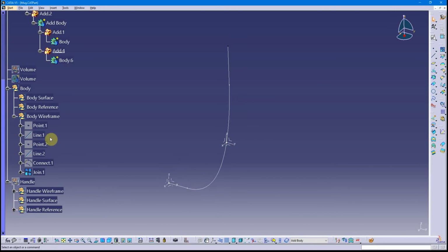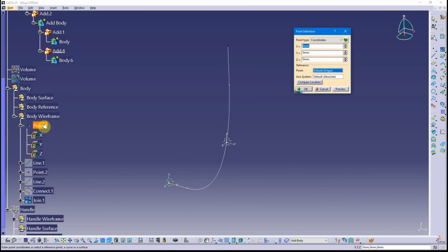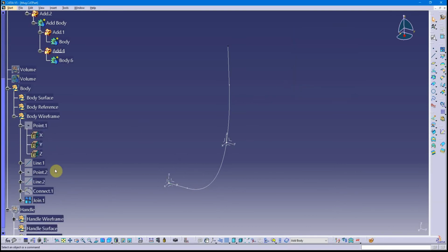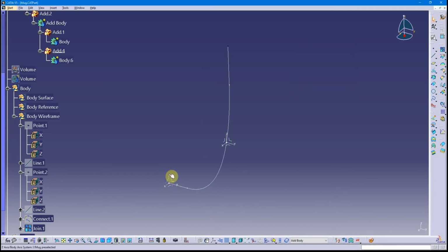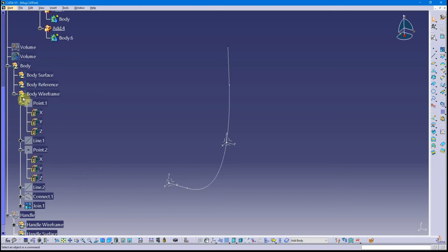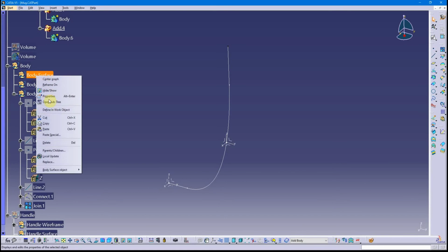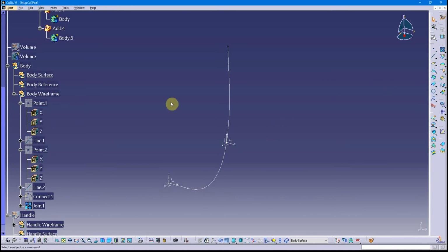Just if you're wondering about size, that first point is at 0, of course. The second point at the top has a Y value of 44.45 millimeters and a Z height of 101.6 millimeters. So that kind of gives you an idea of the sweep and what the volume potentially could be like later. So within my body solidify group, I've got a body surface. I want to make that my defined working location. This is going to be simple. It's just to revolve around the Z-axis.